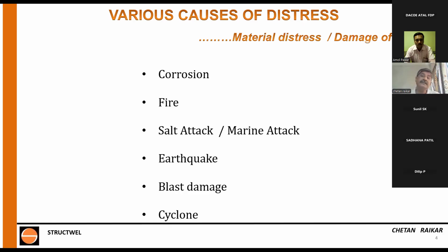Why do we have corrosion in other cities? One is because of heavy pollution, and second, there is a big trend of converting agricultural lands into construction. Agricultural lands have been polluted with nitrates and so many other salts for higher yield in agriculture. So the earth is rich in salt. So the subsoil water that we take out from a bore and use in construction is extremely bad for concrete.